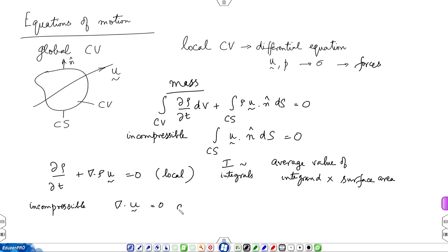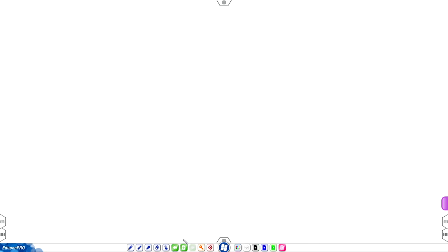the term used so, if the question is whether the flow field is incompressible, check del dot u. If it is 0, it is incompressible. Or alternatively, if it is given that it is incompressible, del dot u is 0. Then we proceeded to the momentum equation.